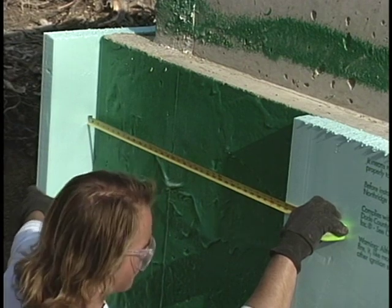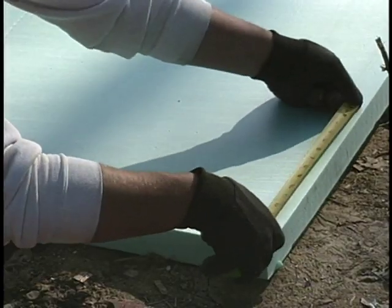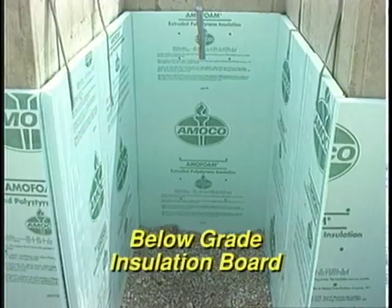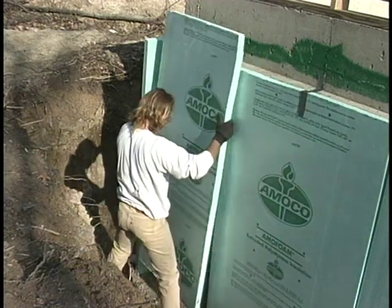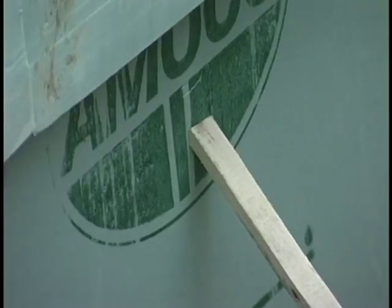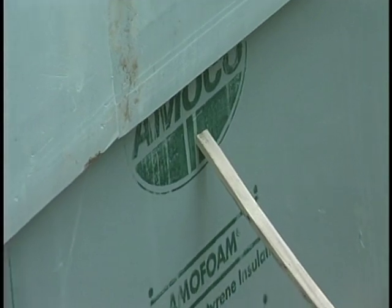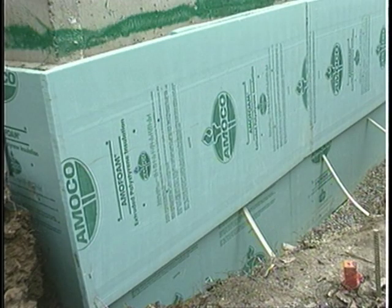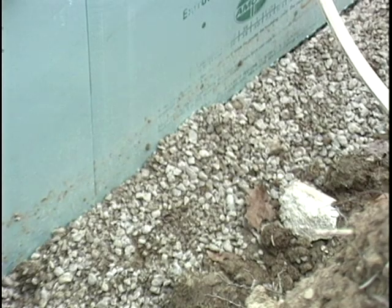In northern climates, foundation walls are often insulated to prevent heat loss through the basement wall. Special below-grade insulation board is normally placed onto the foundation wall right after waterproofing. If needed, pieces of wood can be used to hold the insulation board up against the foundation. This wall has been double insulated along the top half where the wall is exposed above the frost line. Less insulation is needed deep below grade.